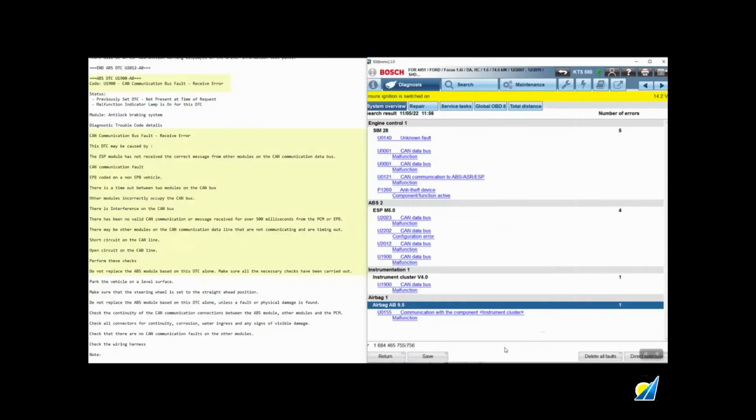One last word on the diagnosis before we move on to the fix, and that is scan tools and just how they present data. And of course, on the right we've got Bosch. It's a very good tool, very good generic tool. It's just how we actually list fault codes and present additional data. And here we can see a number of unknown CAN communication faults.